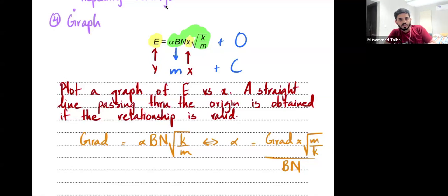All right. In an AC supply, how will we measure frequency? Again, an oscilloscope. You use a time-based setting, you find the time period, and then you take the reciprocal for frequency.